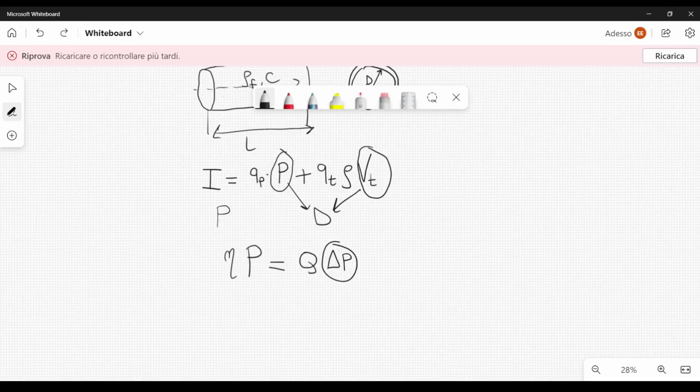So this delta P here is thought to be positive. And you have to remember though that the pressure of the fluid is going to decrease as the fluid passes through the pipe. That's important. So that's why we need some pumps, or in general a pumping system, to cover for the losses that we have due to this decrease in pressure.